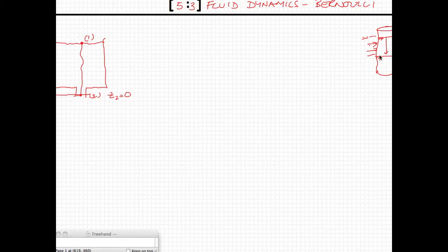And so this happens just to be kind of a diffuse entry into the system, which is kind of this reverse. But if you raise the elevation of this well up to some location, then slowly this would drain down with time to the equilibrium, in which case you'd have flow out of the well and into the formation. And so if you measure the time it takes for that to happen, you have some measure of the permeability. So the permeability is done from a well test, and that's basically the principles used. A bit more sophisticated in the case of this analysis, but the same basic principle.